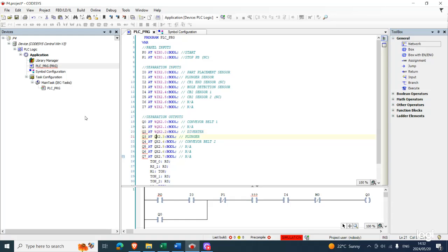You want to make sure that you put in the percentage sign for each and every one of those variables, just to ensure they're in the correct format. So guys, formatting is important. I want you to look at the format of how the variables are written, even the data type. Let's say, for example, your data type is written as an INT. As you know, the inputs and outputs we've been using were all in the form of Boolean, so you should make sure that they are all in Boolean form.